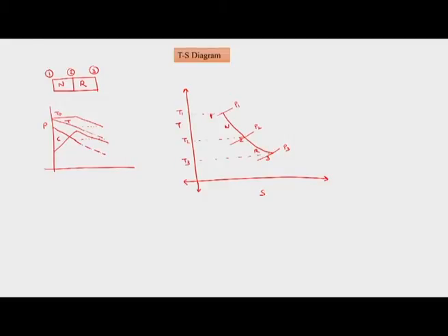But we can also put the associated velocities here. We can put half C1 square upon Cp such that we can go to T01, and then we would have P01. But there is no energy interaction in the nozzle, so we would have the same total temperature at the nozzle exit also, except that due to friction the total pressure would decrease.